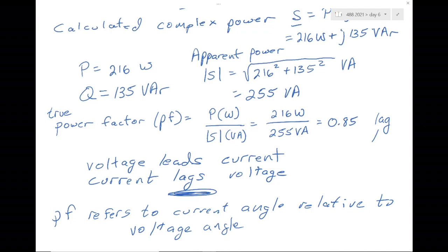That's an extra expense for the manufacturer, and they don't tend to do that. But I tested several, and they all had power factors right around 1. I know they're small induction motors. They're inefficient. So the point of all that discussion is just because it is an induction motor does not mean